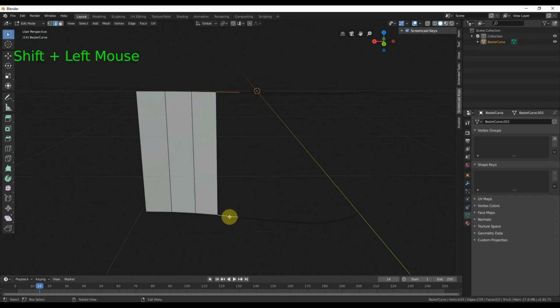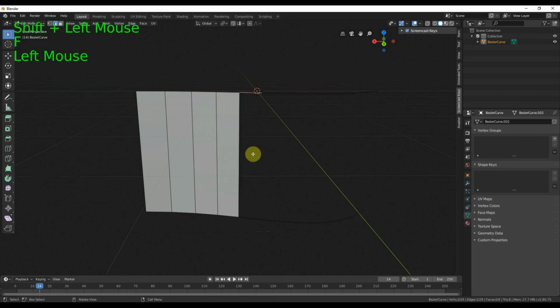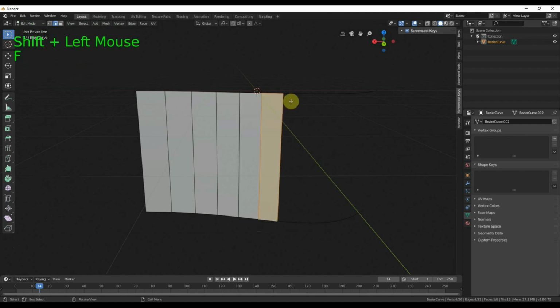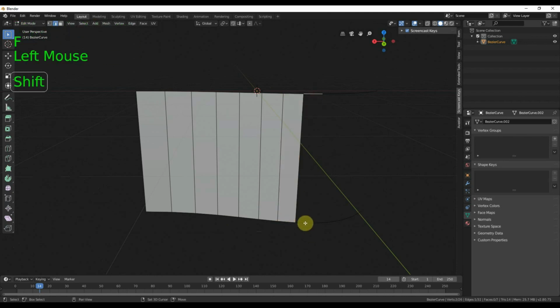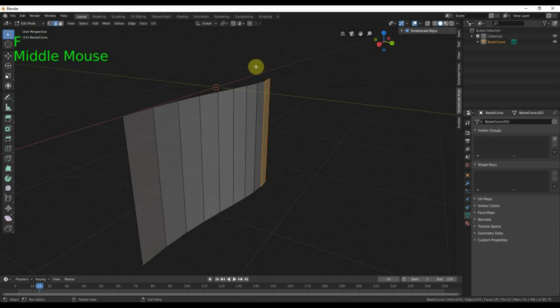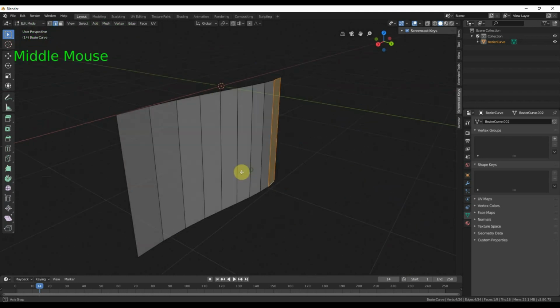End-ons are bad because when you go to upload them into Second Life, the uploader doesn't really know what you intended and can join wrong vertices where you hadn't intended them. So it's always far better to make a mesh. Obviously this way is a bit slower. It would have been far easier to just use the one curve and extrude it down.